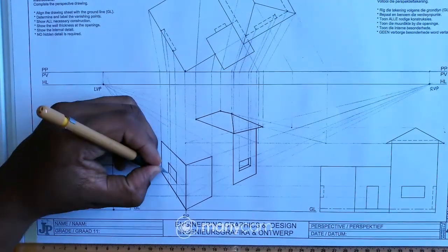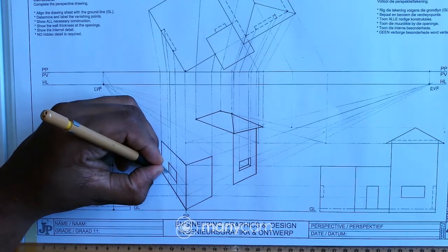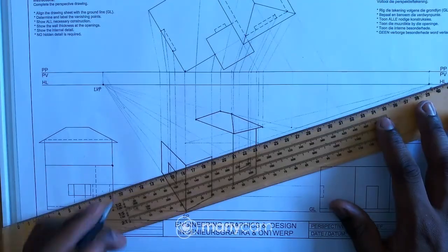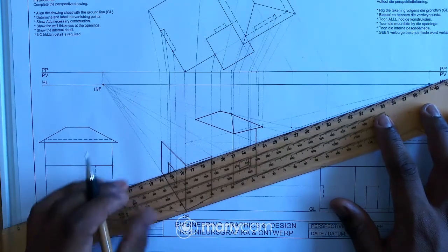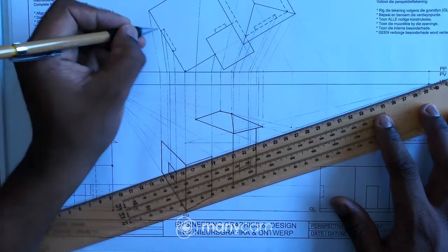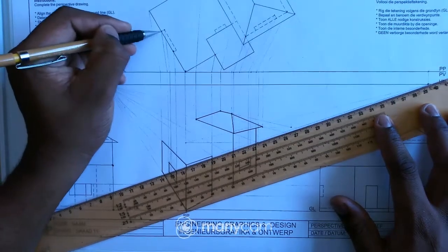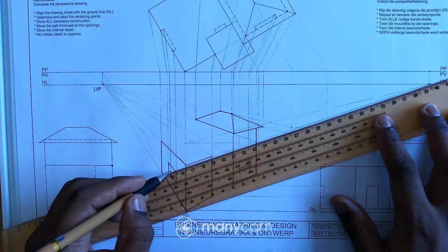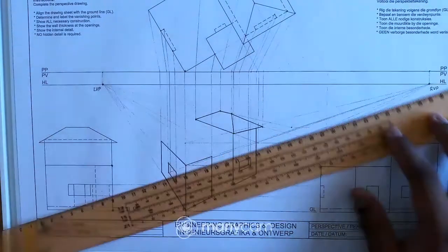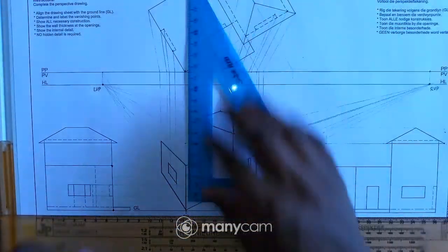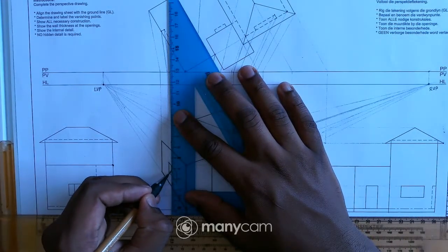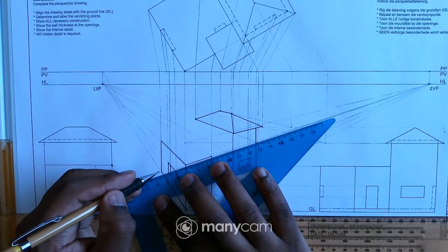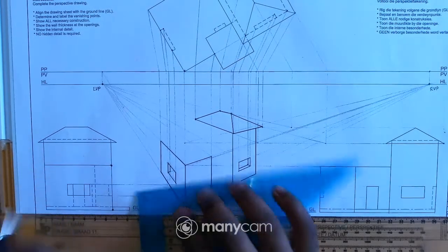And I will project this point to my right vanishing point. Why to my right vanishing point is because from this point there is a line that is going up towards my right hand side. So I can just take this to my right vanishing point. So I have a frame there, and I can draw the frame using solid lines.